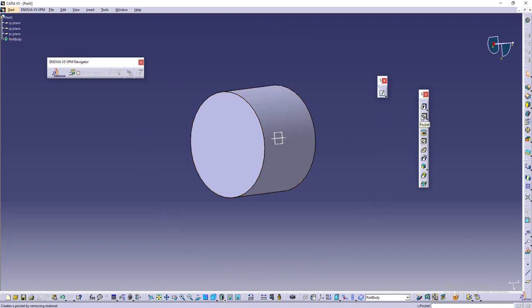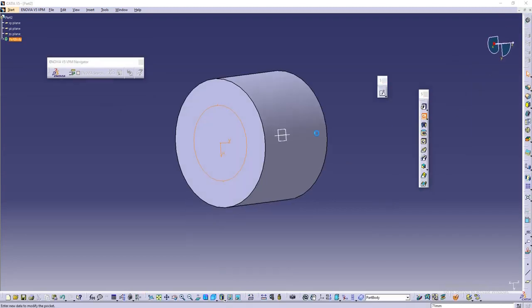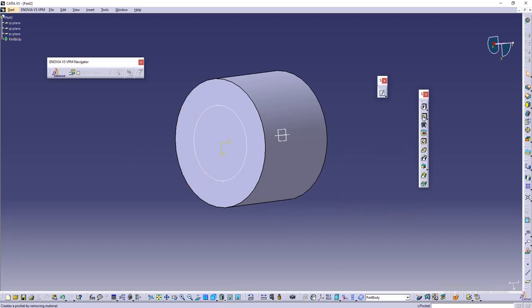So if I click here, go to the sketch, I can create another circle, right? Remember, constrain, give some dimensions, back. Now it is showing, okay, extrude only, right? If I go to the cut, it will just select this, not this, right?